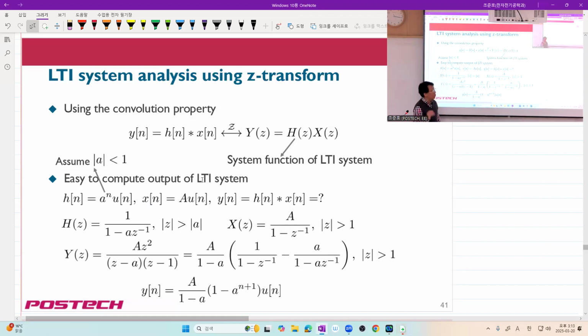And as you know, the region of convergence of this output may be bigger than the intersection of the regions of convergence. Now, this is for every DT system, if we view this as the impulse response of an LTI system. We can interpret Y as the output DT signal, X as the input DT signal, and H as the impulse response of the DT-LTI system.